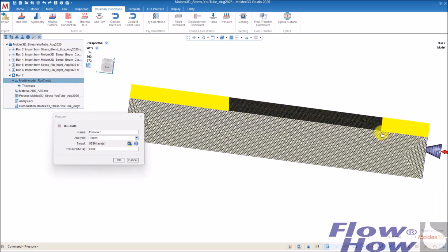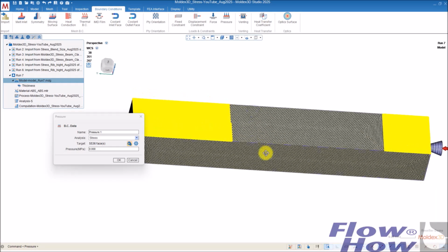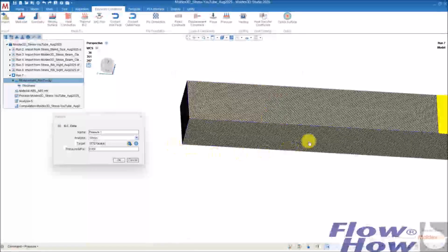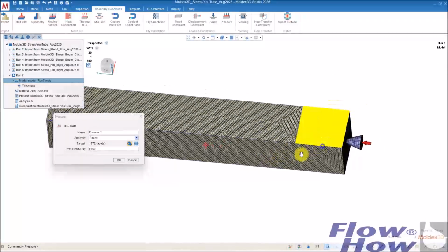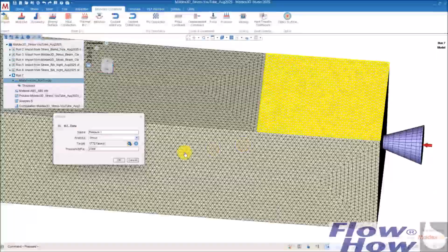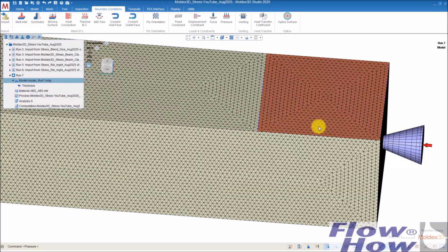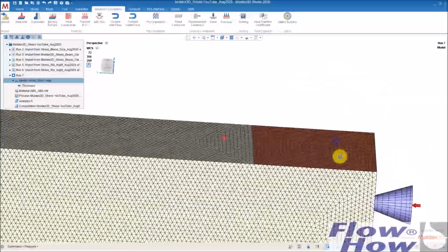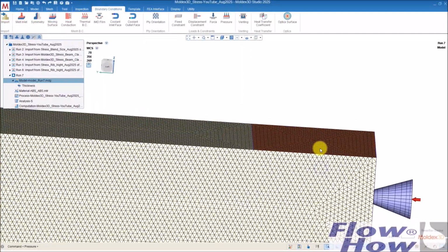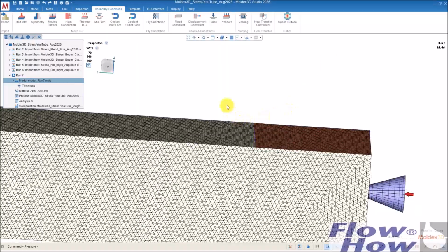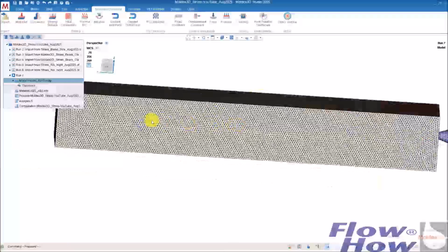You could also extrude this a bit up, then it will be disconnected from the rest of the surface and it's much easier to pick it. But anyway, I'll just put in the pressure 0.127, like that. If you put in a minus pressure, you don't push down, but you'll just pull up. So you can just put minus in front of it, not a problem.